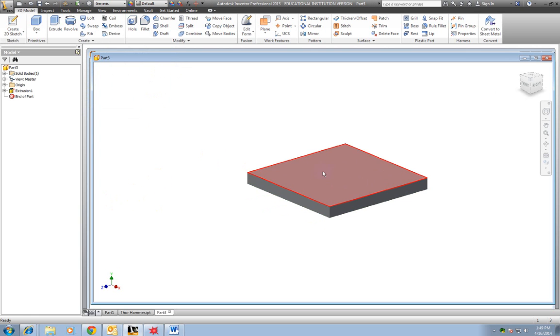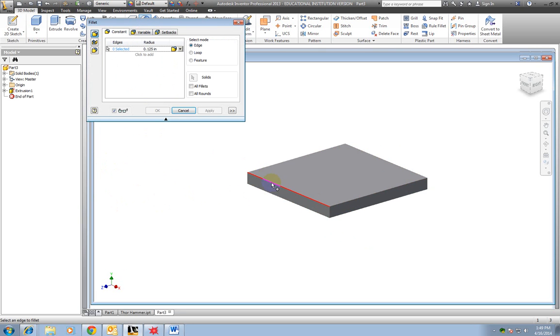Now I'm ready to add the circle on it. Actually, let's go ahead and do the fillet. Kind of make that a curved surface. So I'm going to click Fillet, and I'm going to click all the edges that I want to fillet. Right, and now I can't make this just 0.125 because say I make this larger and it's like 2 foot instead of 2 inches, 0.125 is not going to look the same. So I'm going to make this D0. Let's divide this by 10 as well, just because I did that with the height. So if I want it to go down to the bottom, that would also be divided by 10.